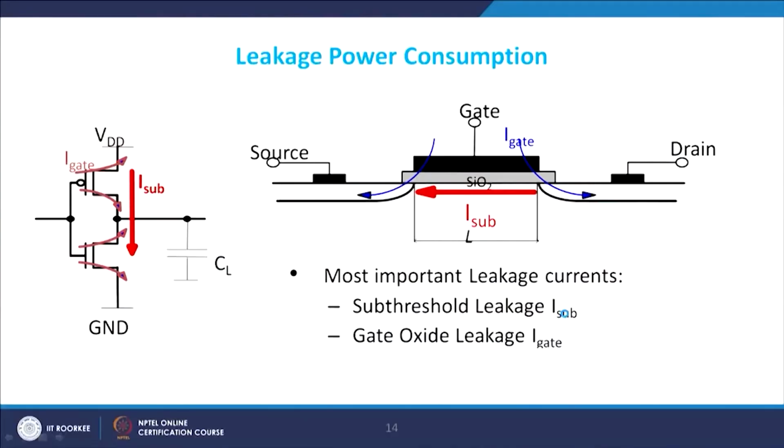Let me come, therefore, to the leakage. So, I had saturation in which the gate voltage was very large or very small, and therefore the output will be either switched on or switched off. The second issue which came up was that of the static power dissipation, short circuit power dissipation. When both the devices are equally on, you will have a direct path between the two, and you end up with leakage power, which is a subthreshold leakage.